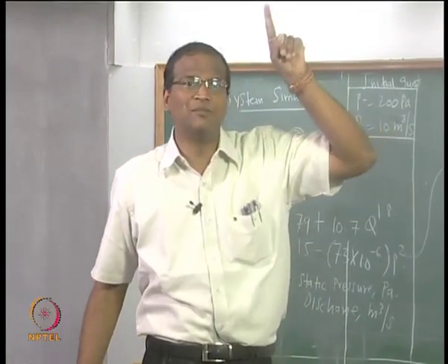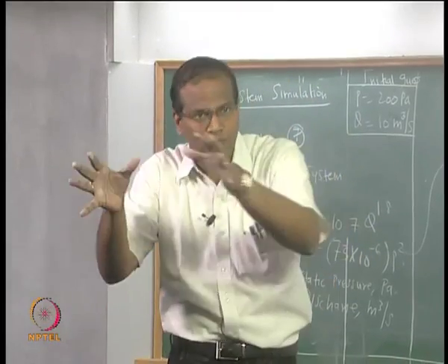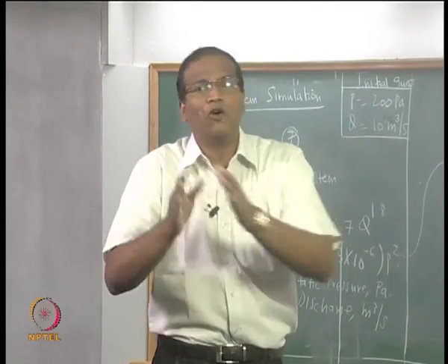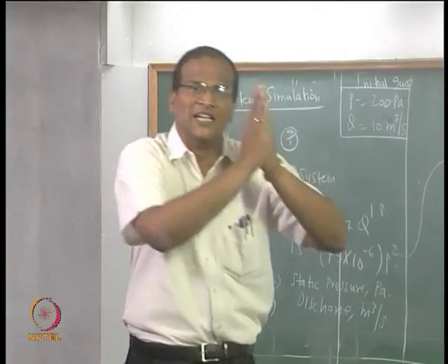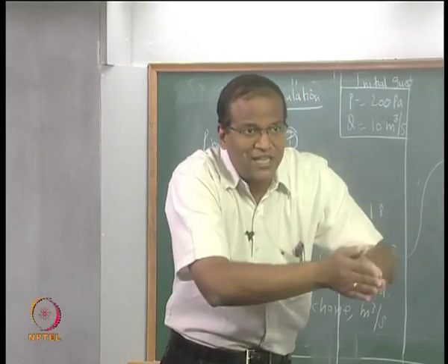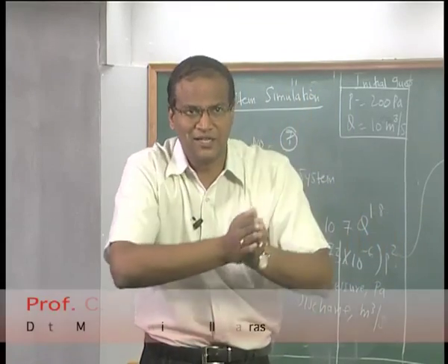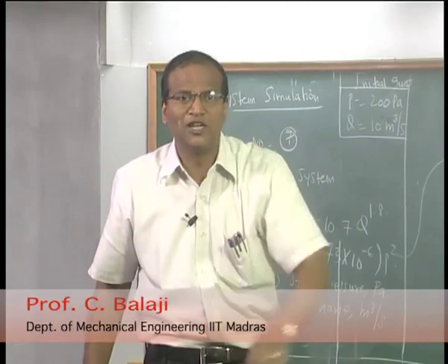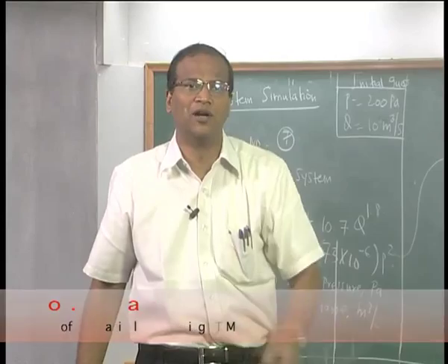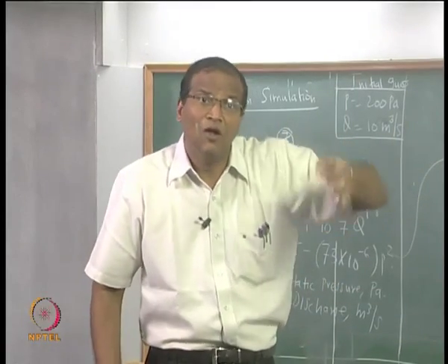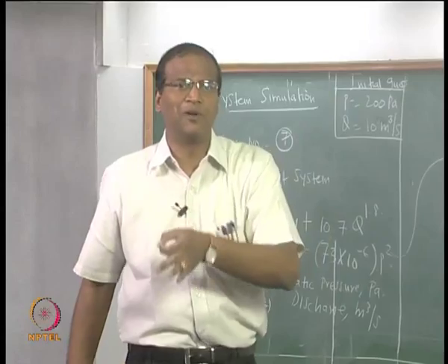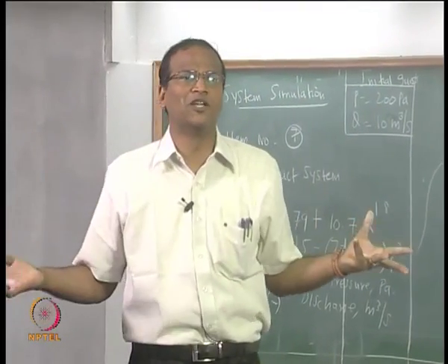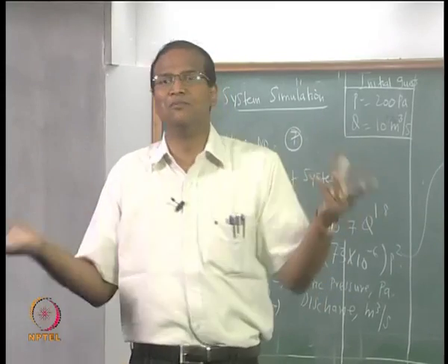So you have to take additional measures, you will have to validate your solution. You apply your numerical technique to some other problem for which either somebody else has done experiments or analytical solutions are possible. After you run through so many iterations and incorporate your stopping criterion, you get a solution which is exactly the same as what other people have reported, or the analytical solution. Then you say, for this particular problem, when I apply this stopping criterion, my solution works. Therefore, when I apply it to an actual problem for which I do not know the true solution, there is no reason why it should misbehave.